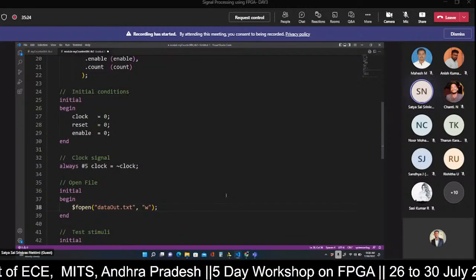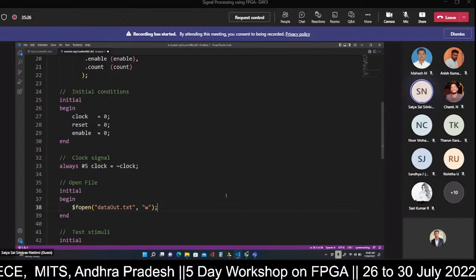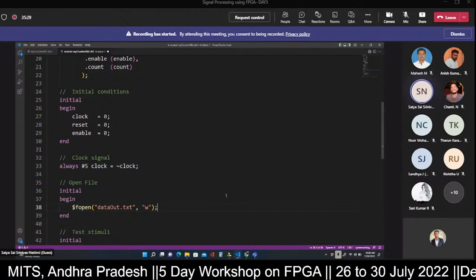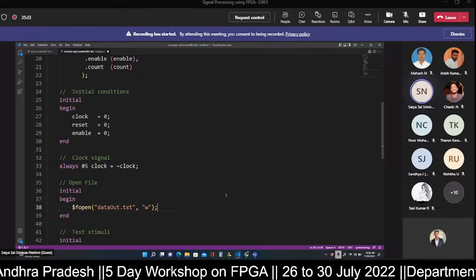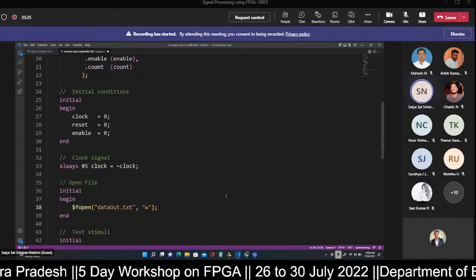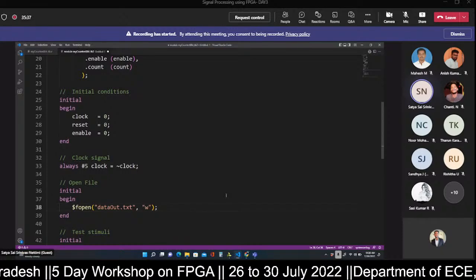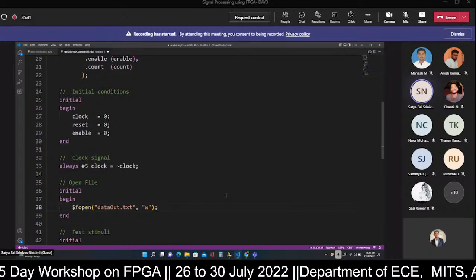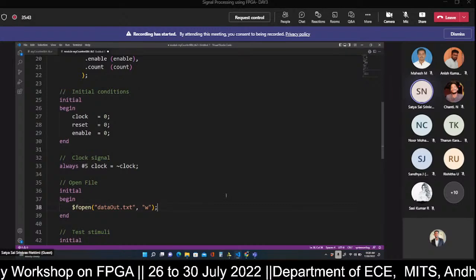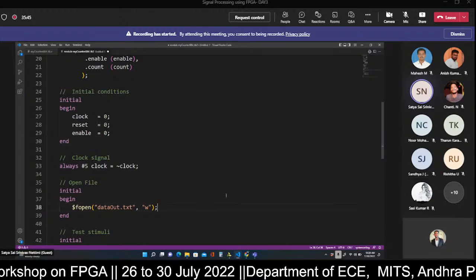For example, within the module you will be doing n number of test benches and n number of simulations. Whenever you run separate test benches, the common directory will remove all the files of the previous simulation carried out by a previous test bench.